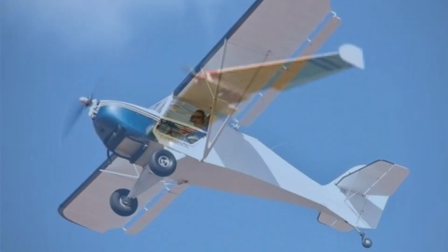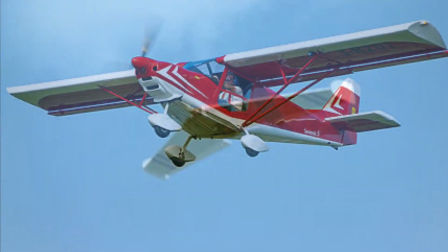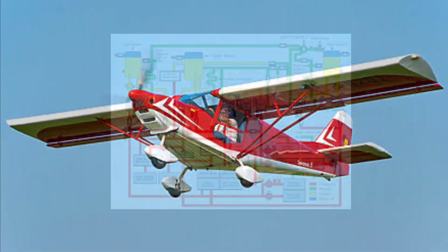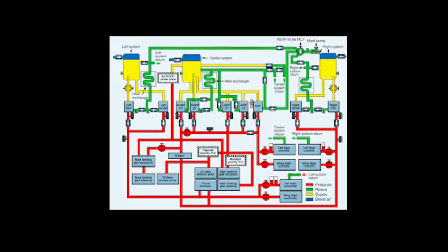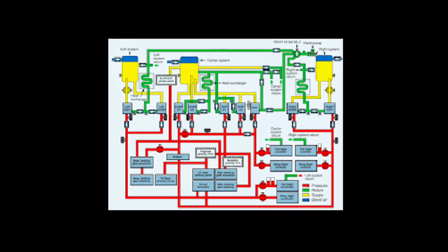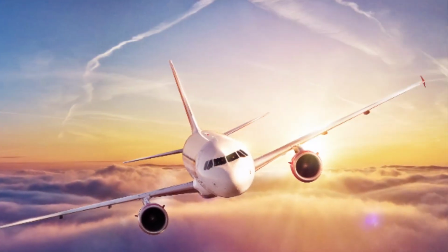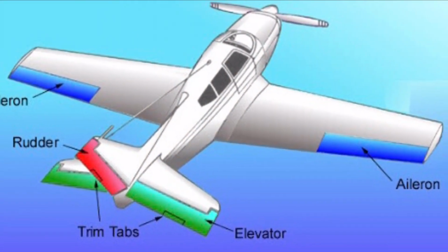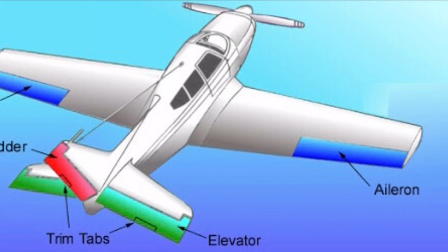They are like elevons. Elevators and ailerons combined together. Flaperons. Flaps and ailerons combined. In larger planes, all these controls are controlled by using a hydraulic system. How the hydraulic system works is for another video. Aircraft rotate about their center of gravity depending on the axis of rotation. Aircraft change direction by making the plane imbalance and rotate on its axis.